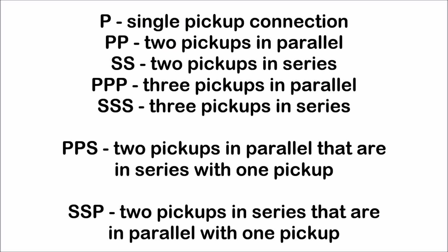Connections shall also be referred to by the first letters of the connection and the number of pickups involved, P for single pickup connection, PP for two pickups in parallel, SS for two pickups in series, PPP for three pickups in parallel, SSS for three pickups in series, PPS for two pickups in parallel that are in series with one pickup, and SSP for two pickups in series that are in parallel with one pickup.